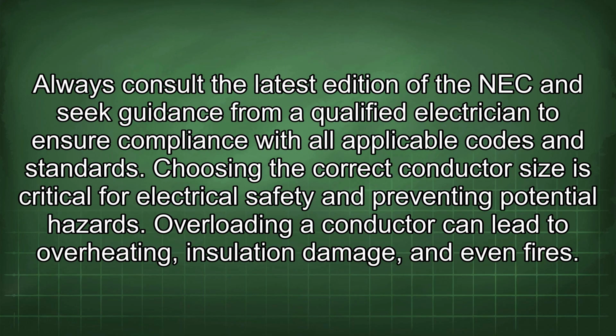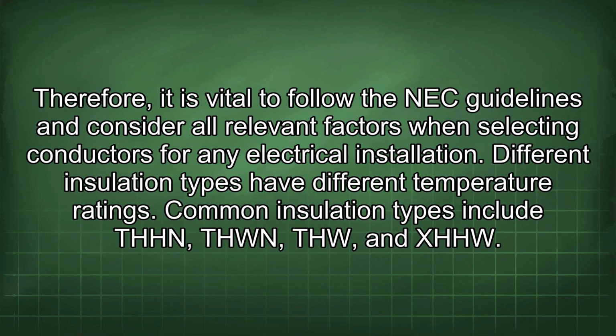Always consult the latest edition of the NEC and seek guidance from a qualified electrician to ensure compliance with all applicable codes and standards. Choosing the correct conductor size is critical for electrical safety and preventing potential hazards. Overloading a conductor can lead to overheating, insulation damage, and even fires. Therefore, it is vital to follow the NEC guidelines and consider all relevant factors when selecting conductors for any electrical installation. Different insulation types have different temperature ratings.